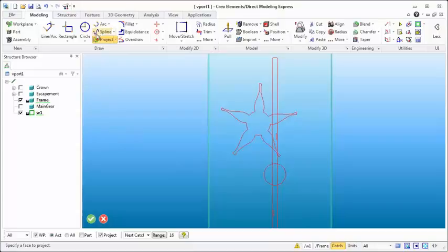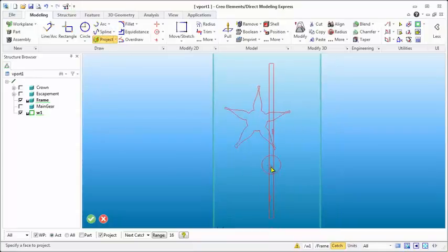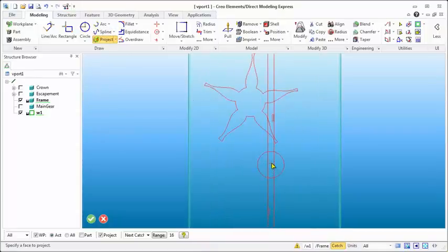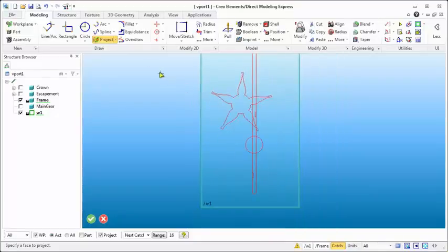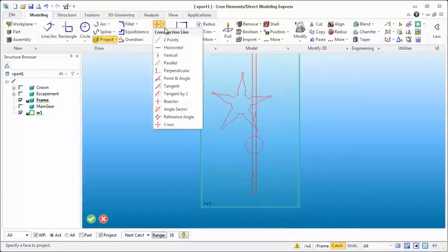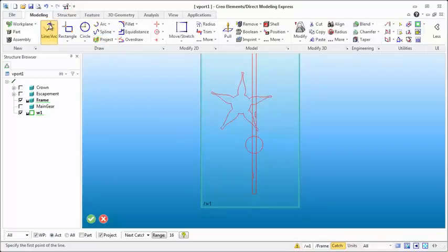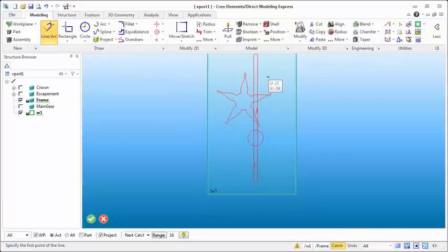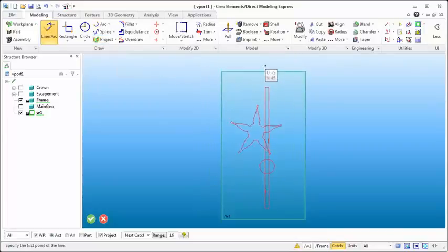So now we've gotten this geometry, I know that I'm going to need a spot here for the axle. We're going to modify this pendulum shaft here in a bit, but we need a space for the axle to come through here and here, and I also want it to be something of a curvy shape. So first thing I'm going to do here in this case is I'm just going to start drawing some lines, and you can come in and draw lines based off of all this stuff, but even if you just use the standard line and arc, I'm going to just get some foundational geometry that I can use here.